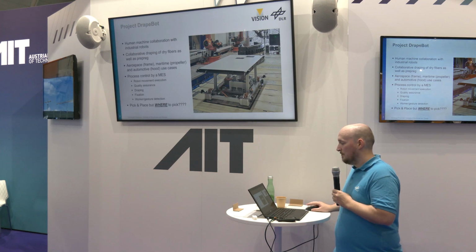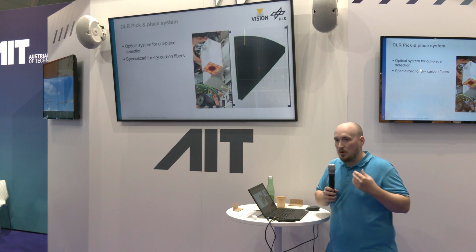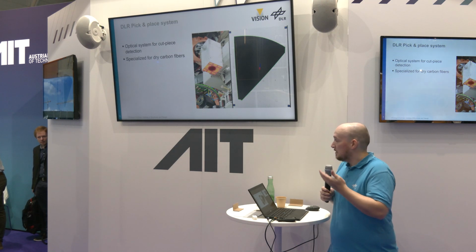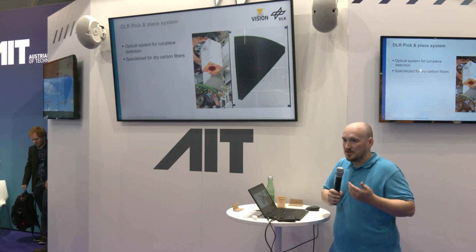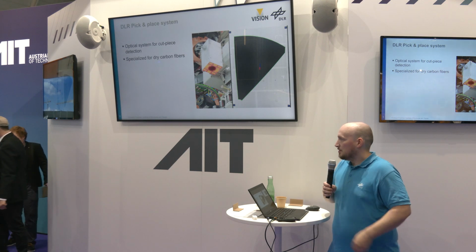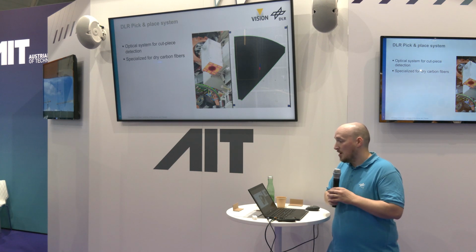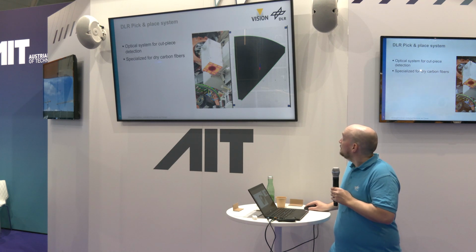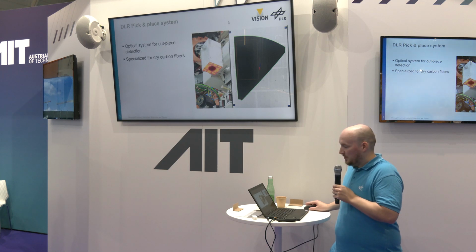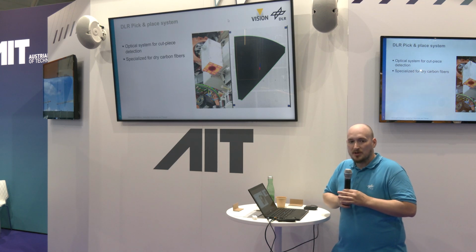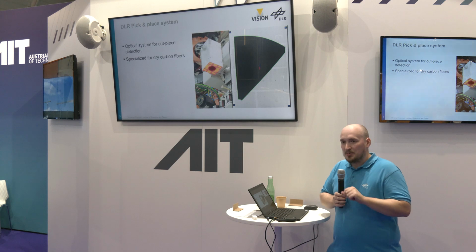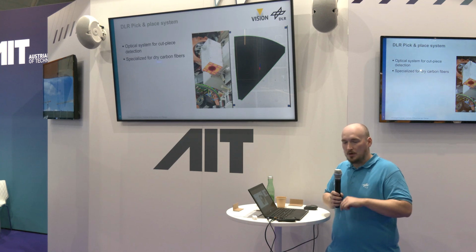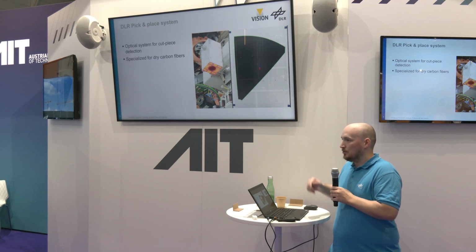So we introduced a new system, which we already developed at the German Aerospace Center. It's a rather standard industrial camera with some polarization filters on it, and a red flash that's good for reflections of the carbon fibers. And you see in the corners of this image these markers. They are calibrated to the robot and to the camera, and then we detect the cut pieces by rotation and template matching where they lie on the table, and then the robot also knows where this ply is lying due to these markers.